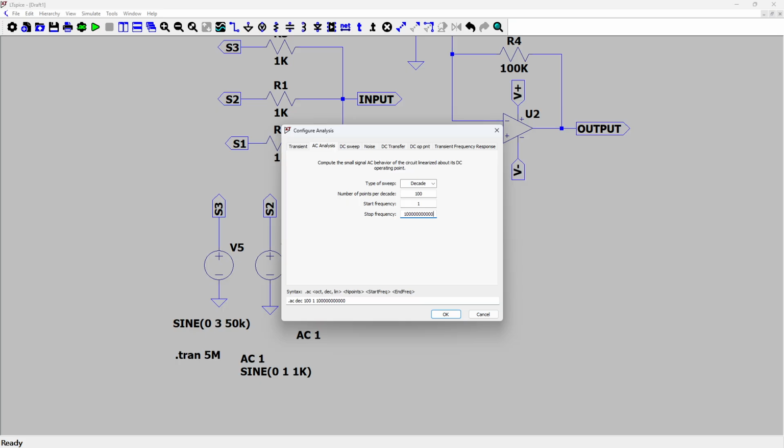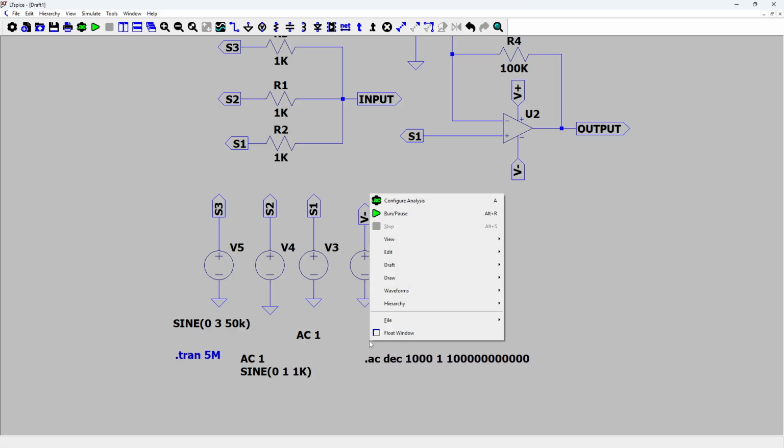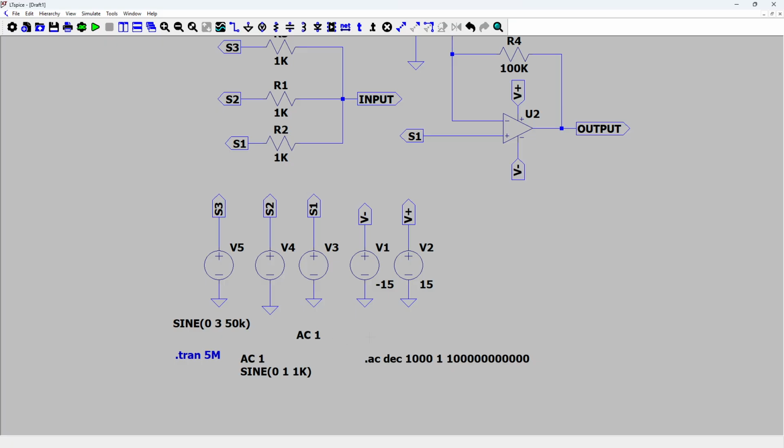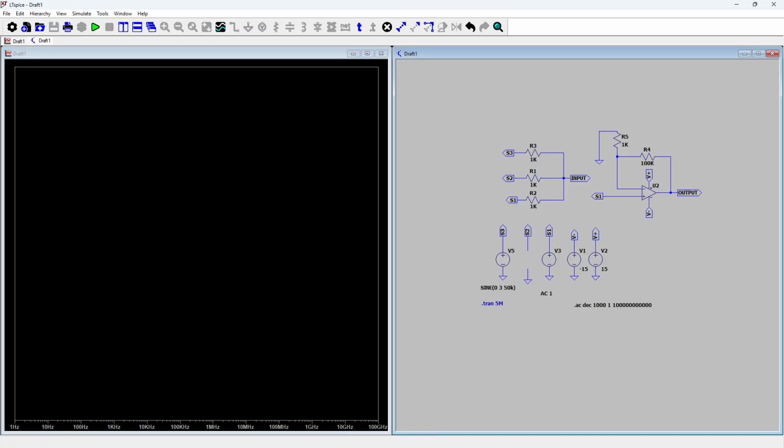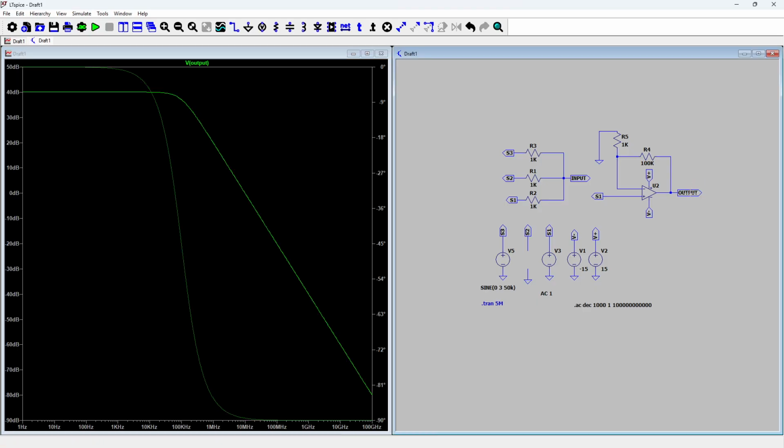Let me have just that frequency. Let me add 1,000. So let me have it here. No need to, so I can delete this. If I run that, I can see that to find the output. You can see that's what I needed. You'll see that it does not amplify every signal. It reaches a point whereby the signal that you have into a system cannot be amplified. So that's how you can run an AC analysis and visualize the gain bandwidth of your